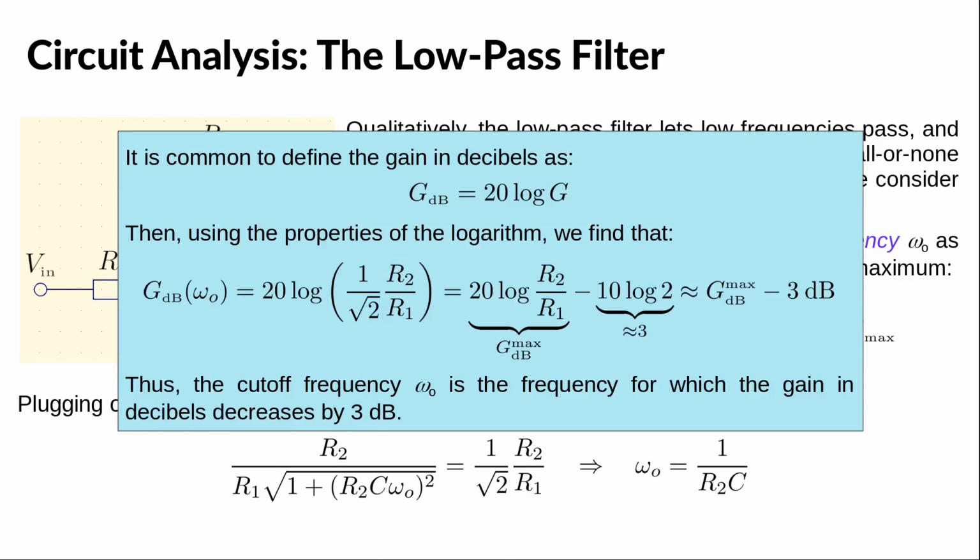Why 10 times? Because we are talking about the decibel, 1/10 of a bell. A bell is a unit that is too big, so we like to divide it in decibels. Why do we take the logarithm? There are two main reasons for that. The first one is that it makes it easy to analyze the asymptotic behavior of the filter, but I won't discuss this here. And the other one is that our ears are more or less sensitive to the logarithm of the power and not the power directly. So to multiply the loudness of a sound by 2, we need to multiply the power by 10.